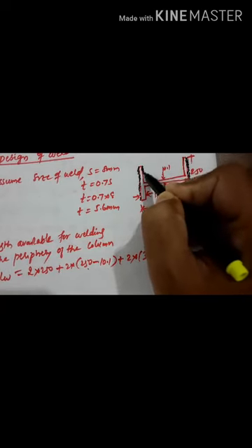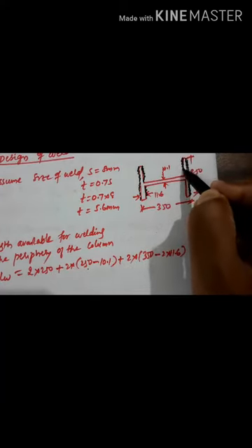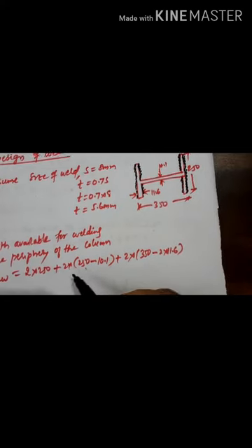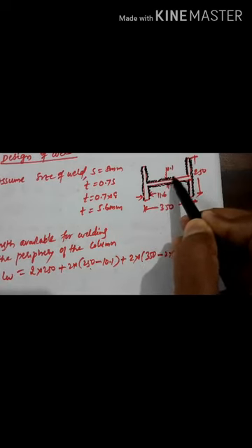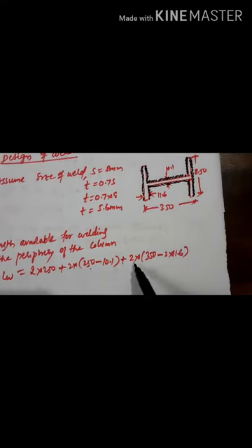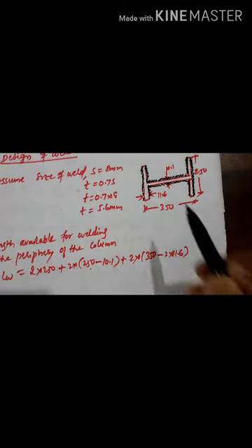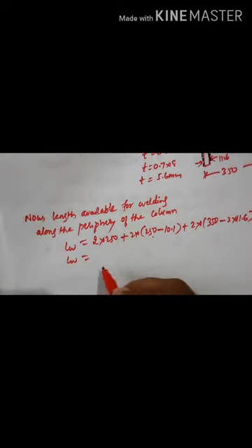Then here if you want to weld, 250 minus 10.1, and this side 250 minus 10.1, that is 2 times. The next, here you have to weld. This is the length available for us to do the weld: 2 into 350 minus 2 into 11.6, this side 11.6, this side 11.6. Then the length available will be 1633.4 mm. This much is the length available for us.